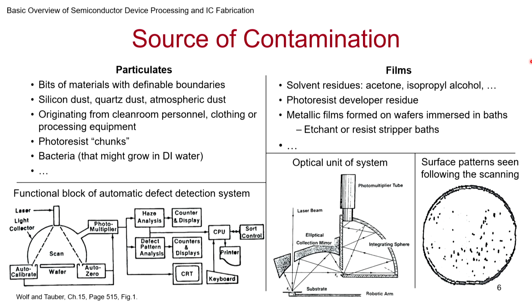Of course, these are easy when the wafer is pristine and you're starting off with a plain wafer. When there are patterns, it becomes more tricky, but this at least highlights what is out of the way, and then you can analyze this and go back and see what's the source and get rid of the source of contamination, and also make sure the wafers are cleaned appropriately.